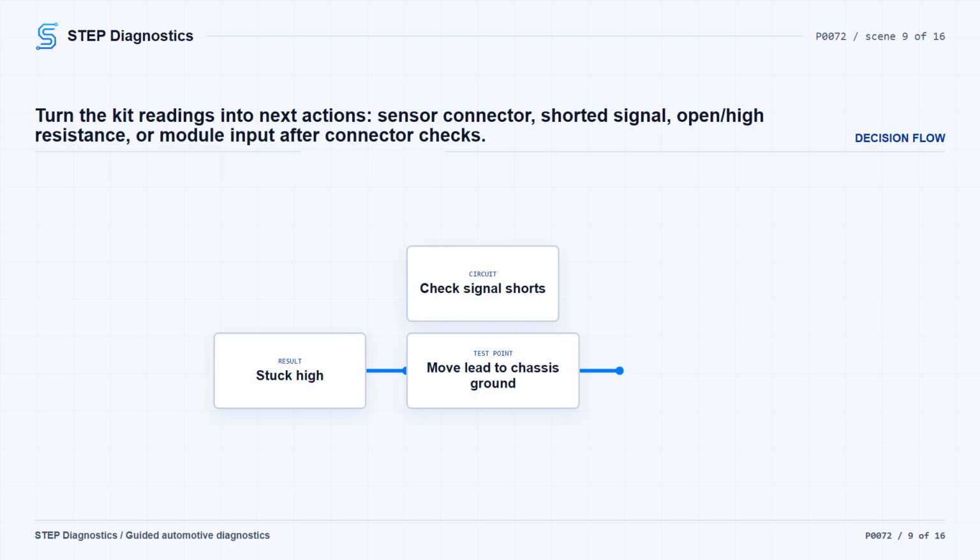If the voltage drops to 0.0 volts, the resistance is in the temp sensor ground circuit. If voltage is still present, the resistance is in the temp sensor signal circuit. Check the appropriate circuit for high resistance. Typically, it should be less than 3.0 ohms.